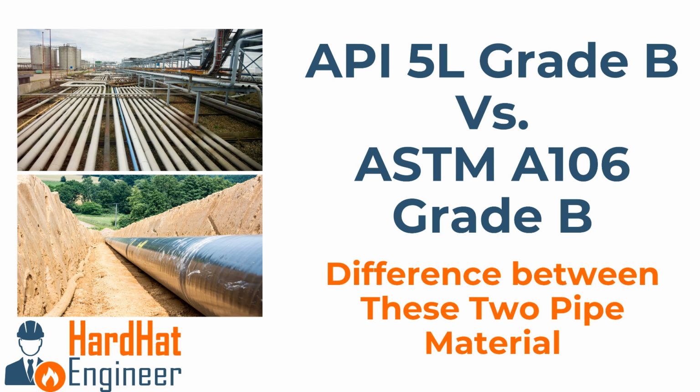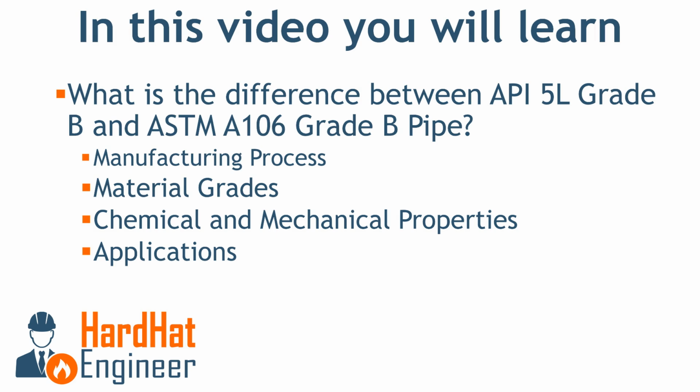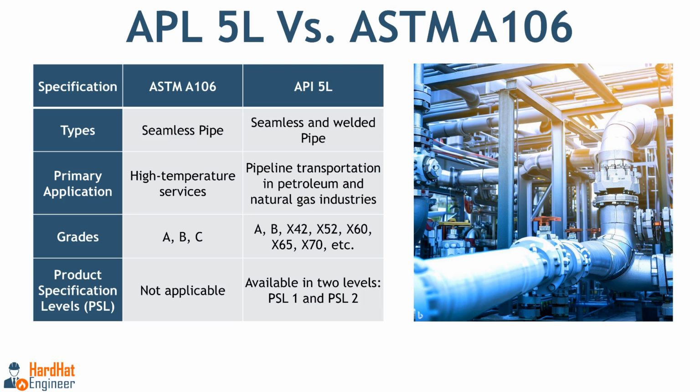I will explain various aspects, such as the manufacturing process, grades, chemical and mechanical properties, and applications of these two pipe materials to highlight their differences and similarities. Let's get started. ASTM A106 standard is specifically for seamless carbon steel pipes used in high-temperature services. API 5L standard covers both seamless and welded steel pipes that are primarily used for the pipeline transportation systems in the petroleum and natural gas industries.